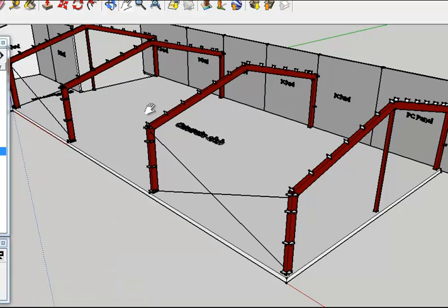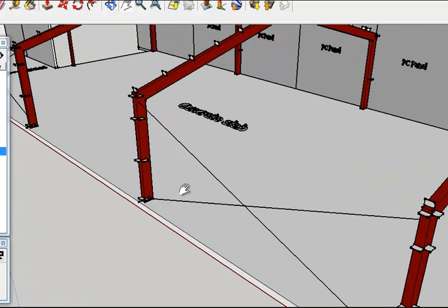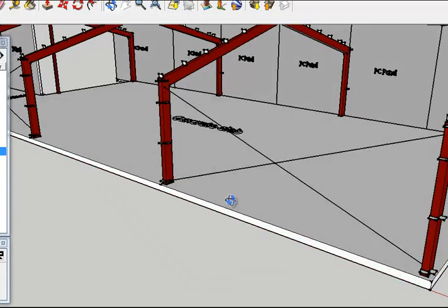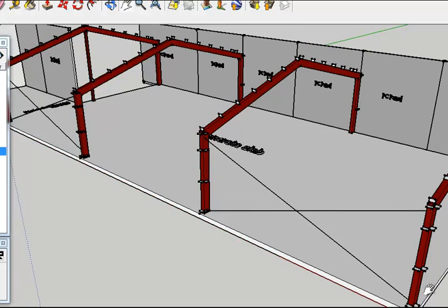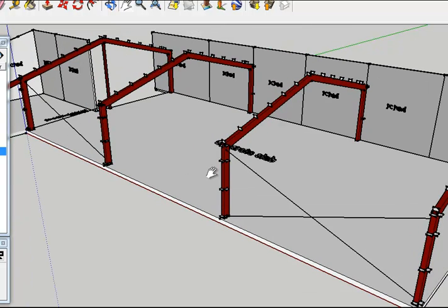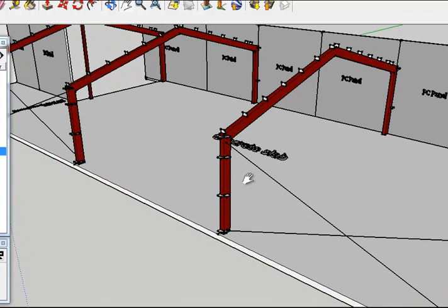One of the problems, of course, with this type of construction is that it doesn't have a lot of lateral support, and so there's the opportunity for frames to pivot at this point here and tip over. So we get around that by putting in steel bay bracing. Okay, so in this case I've shown it in two bays. These can actually get in the way. If we wanted to have a type of construction where we had windows through here, then we'd have to position the windows to avoid these braces.